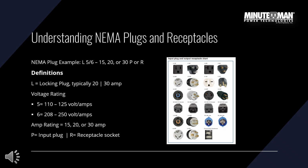The NEMA numbering system includes NEMA, then a number that represents the configuration, a dash, the number that represents the amperage, and then a letter that represents the type. Let's break down an example. If you see NEMA 5-15R, the 5 is the voltage and configuration type, the 15 means the device is rated for 15 amps, and the R stands for receptacle, or there will be a P if it's a plug. So a NEMA 5-15R is a standard 120 volt outlet you'd see in most US homes.